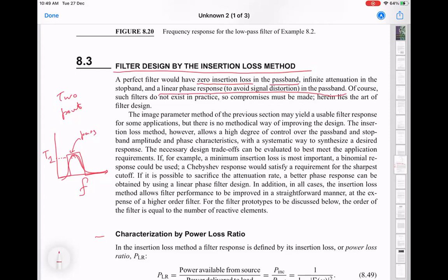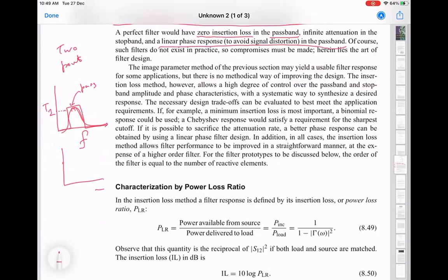So this, of course, is band pass, but you can have low pass or high pass as well. Okay, so this is low pass, high pass. So this just tells you which frequencies are cut off and which frequencies are propagated. So low pass means it passes all frequencies below a certain cutoff frequency. High pass is the opposite of that. Band pass is, again, some range of frequencies it allows, which is not going down all the way to 0.